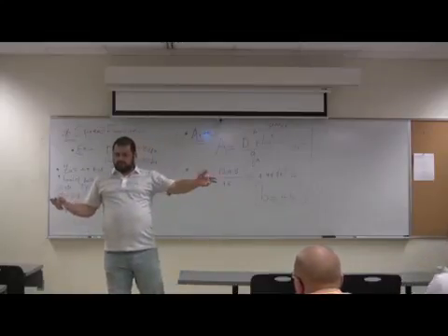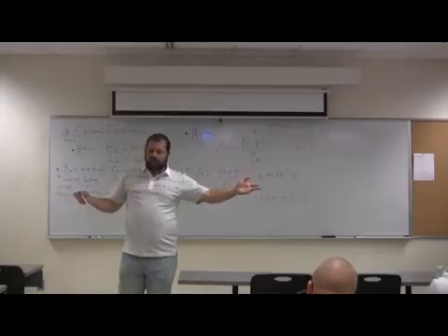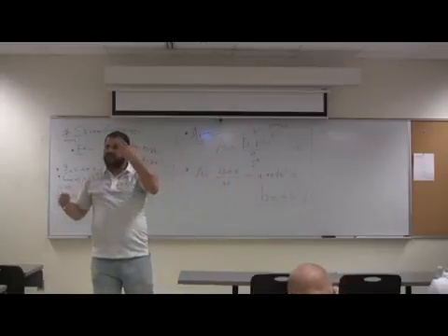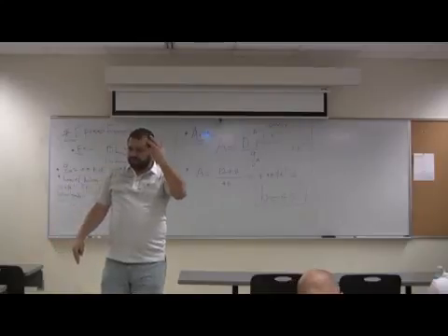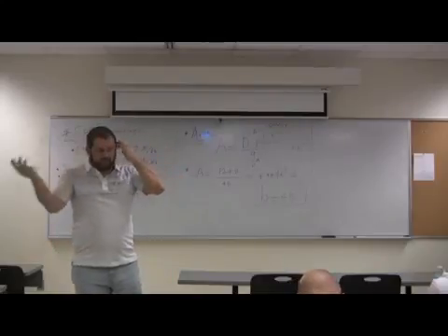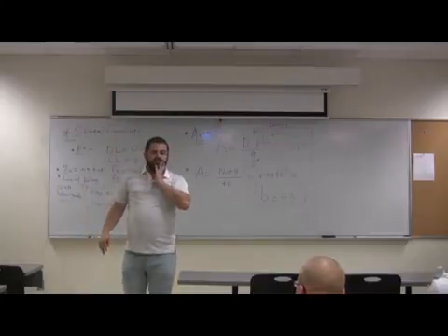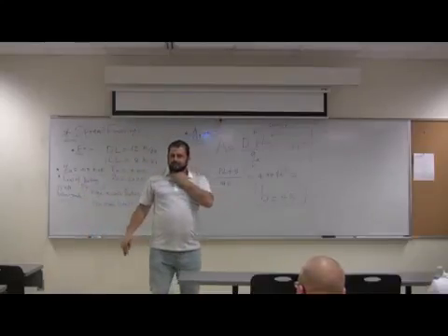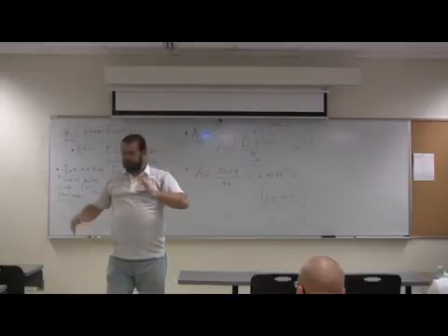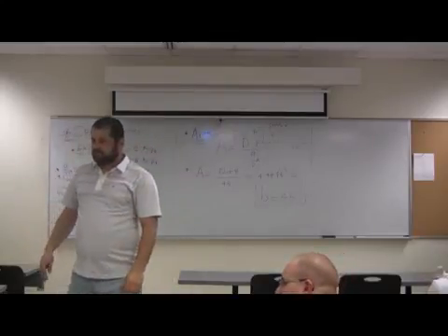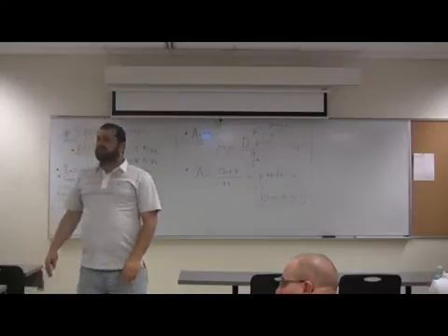So there is 0.15 kip per square foot from the concrete. And then we have 3 feet of soil. The question I should ask is, what's the unit weight of soil? 100? It's like 66. In English or metric? Did we deal with metric? No, in soils, all we do is metric. We haven't done any English. In pounds per cubic foot.